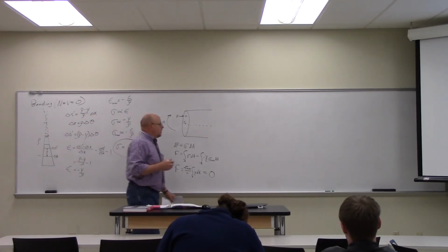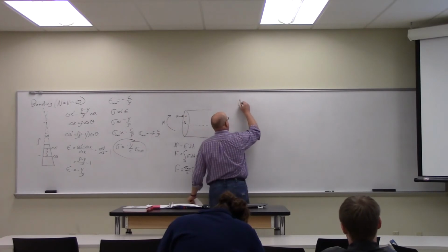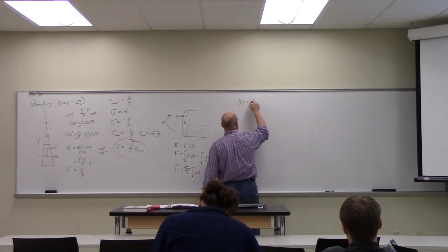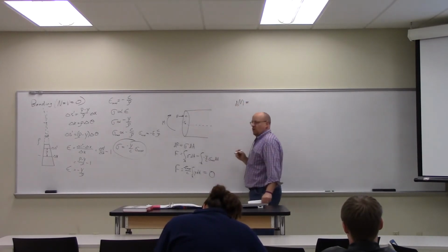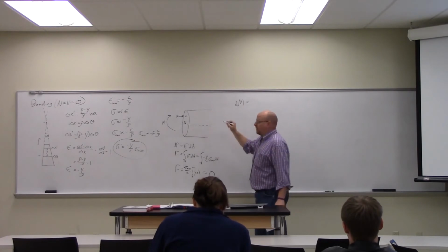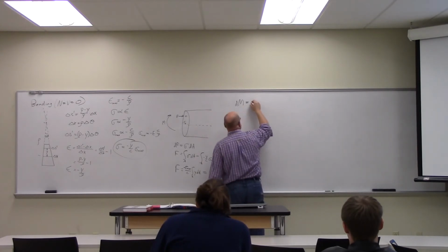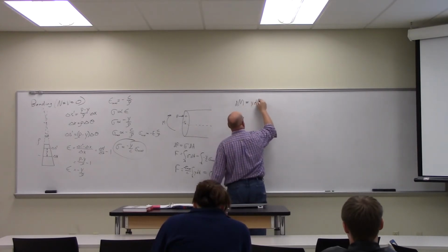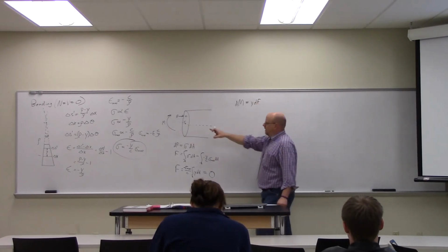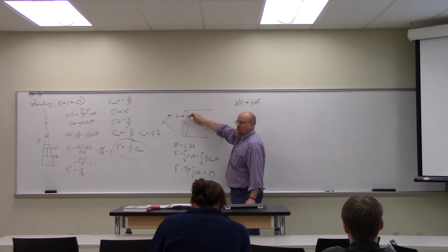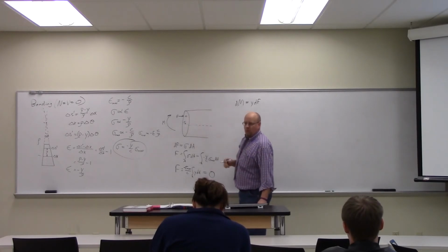So we also know that M, that applied moment, or I'm sorry, dM, the increment of the element of moment created by this force that I've drawn here in this little increment, is going to be y times dF. dF is the increment of force for that little area. y is the distance it is away from the center. y times dF gives us our moment.